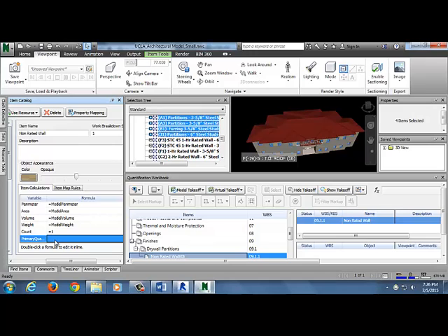So if you know you're only concerned for a drywall partition with the gross square foot, I'm going to make my primary quantity length times height in square feet. Now that's different for counting toilet partitions or toilet accessories. My primary quantity is going to be a count, right?